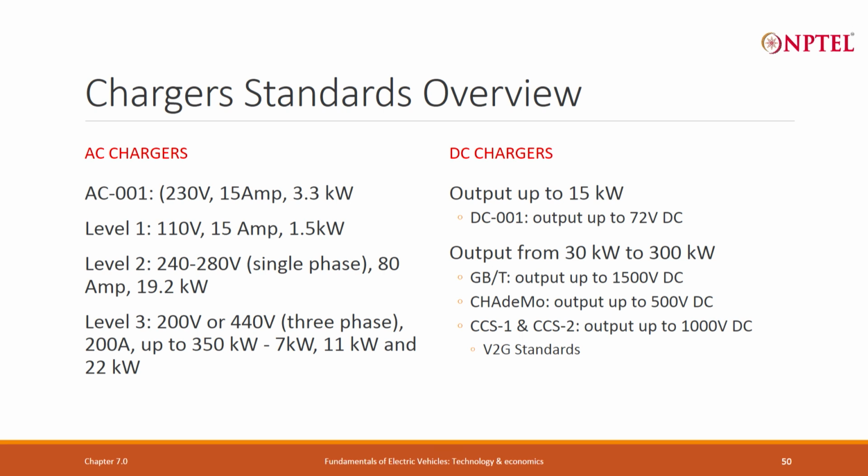The other standards, GB/T, CHAdeMO and CCS, are all from 30 kilowatt to 300 kilowatt at higher voltages. So you see why there was a need for defining the Bharat charger. The very first thing is that our vehicle mix is very different from what exists in Western countries, where the standardizations happened. The standardization ratings of 1000 volt, 500 volt, 1500 volt are largely not the segment in India.